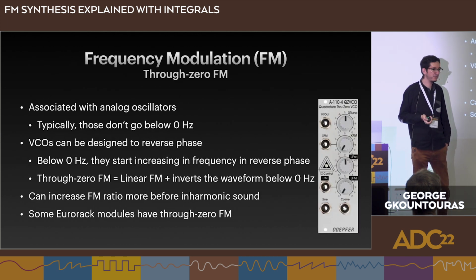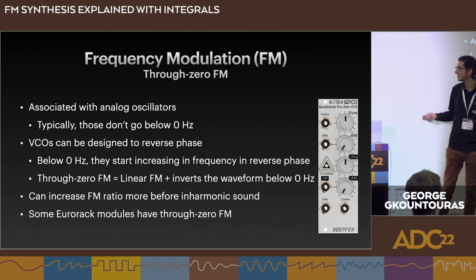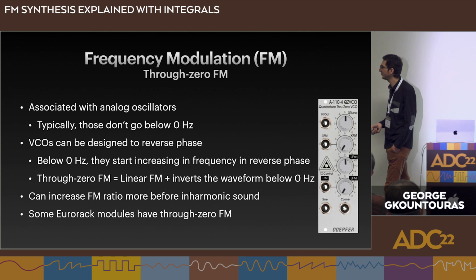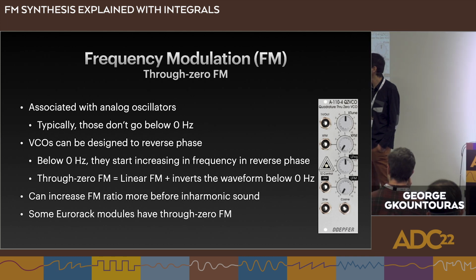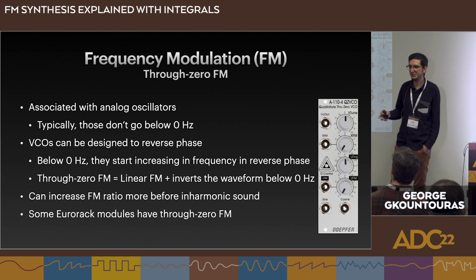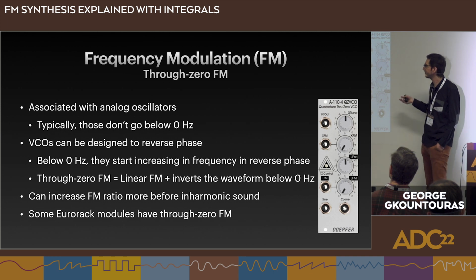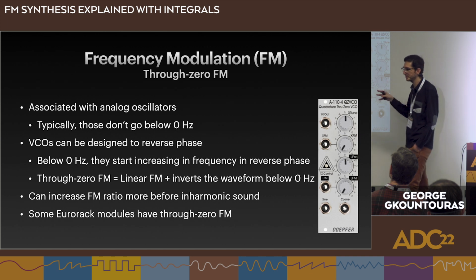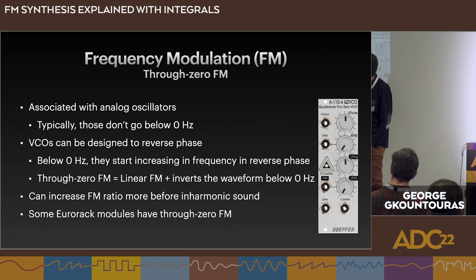So a special type of FM is through zero frequency modulation. It is most commonly associated with analog oscillators, which, if you look up a design for an oscillator, unless it's designed for it, will not go below 0 Hertz. It will just stop.